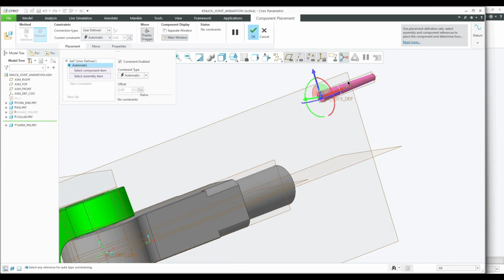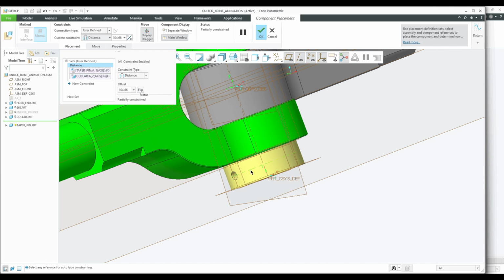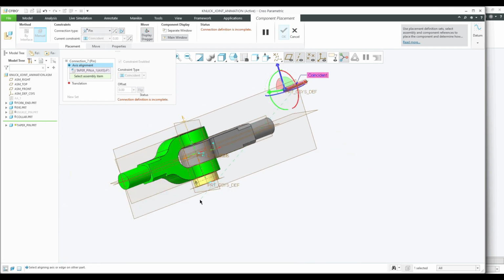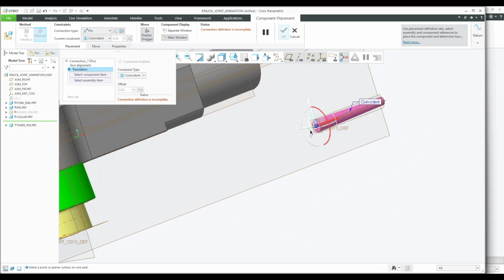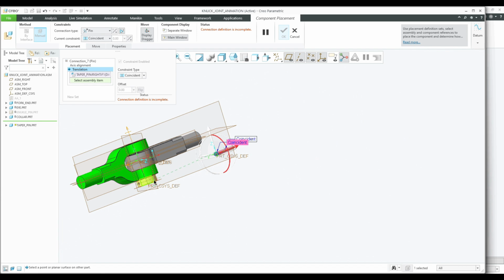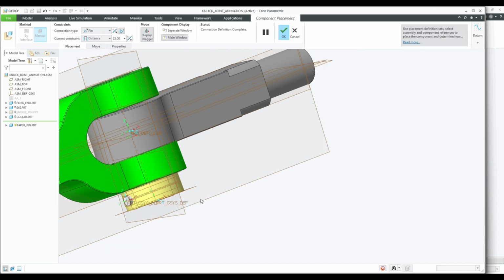In the taper pin also I'm going to follow the constraint of the collar. So I'm selecting this axis to this axis, as a distance. Okay, sorry, I'll just click cancel. No, I'll select the pin connection. For the pin connection I'm selecting this axis to this axis, and I'm selecting a plane to this collar plane, where I will have a distance of 25 mm or 23 mm, like that. So 25 mm I'm placing.